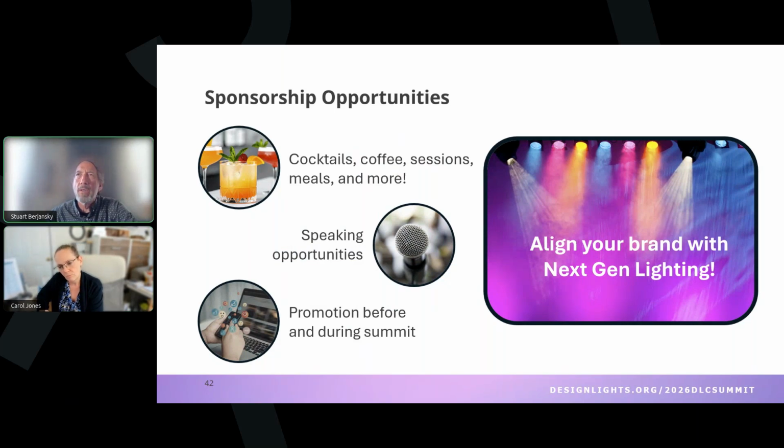Yeah, if I can add, Carol, the typical installation where you're seeing D4i today is like the diagram you had at the very beginning. D4i you're finding inside of a luminaire, where you have the sensor and the driver all communicating within that small, I'll say, package of the luminaire. Where with DALI 2, you may not have all the integrated sensors. You're on the full wired system as you're going through. So it depends from a manufacturer's perspective as to which route you're going, what you're trying to develop, what you're trying to provide for the end users. I think looking at the feature sets of the two also helps to dictate that.